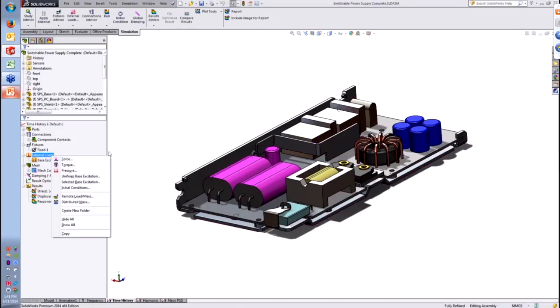We, of course, could specify other loads too. We could specify a shock load or an impact load as a force or a pressure, which also would have a similar curve applied to it, where we would directly input the magnitude, a certain number of pounds of force is applied, like a hammer strike maybe, and how quickly it's applied, which of course is just dependent on how fast you swing the hammer.